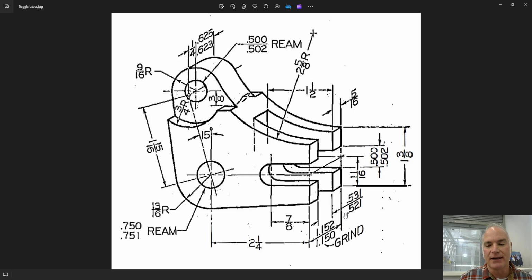When it comes to dimensioning, when you have a dimension that has a greater level of accuracy, you should always use these numbers and not these numbers that have a lower level of accuracy. One other thing that we will do when we create this part is we will use some construction geometry so that we can get things aligned. In order to figure out, for example, this 15-degree angle, we're going to employ some construction geometry so that we can keep these parts in the correct orientation.